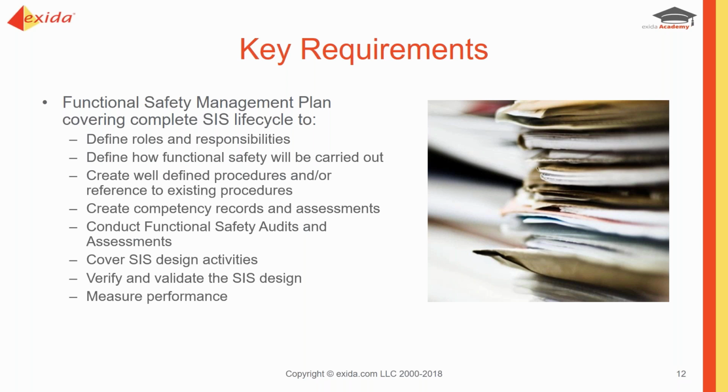A performance-based standard says this is what you have to do, but doesn't define how you do it. However, you need to have some key performance indicators to be able to measure performance such that you can compare it to the original design requirements that are specified in the SRS to see, are we meeting those requirements or are we exceeding those requirements?